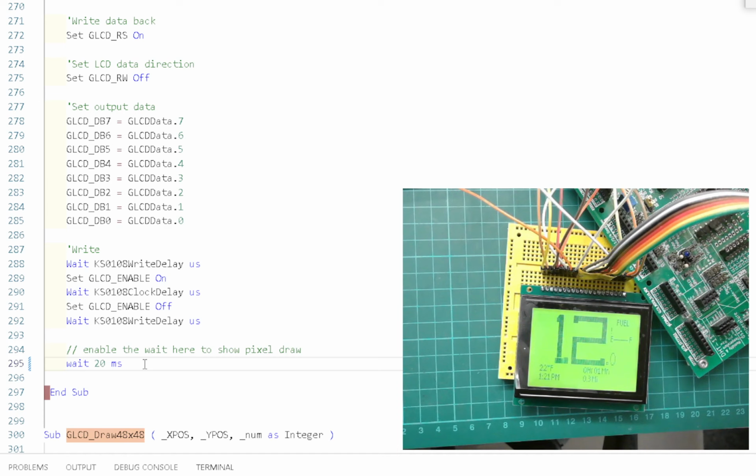And so what it's just doing here is a rundown, initializing the screen. But here's a slower operation. A 2 to a 1 takes a lot more operations quite clearly. And then it's now operating as normal. And if I change the potentiometer, there we go, it's settling down to 27. That must be where the potentiometer was. And I've just changed it to 50 something. You can see it's actually drawing it out. It's reading the pixels in from the GLCD using these private functions, writing them back.